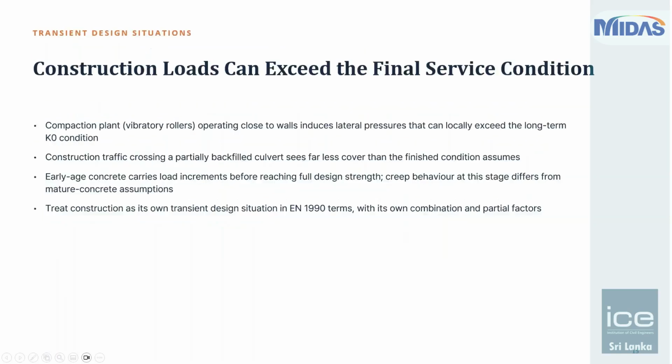Apart from that, there are certain other nuances that we must, as a culvert design engineer, understand. When we use the surcharge for design or the earth pressure for design along with the live load surcharge, right, arising from your vehicular movement, during the compaction action, during the construction stages, it is possible that when compaction is happening, the load might exceed what you have designed for. So the load might exceed the levels for which you have accounted the live load surcharge. Okay, so you will always have the earth pressure along with that the live load surcharge. What if the compaction plant load rises above the live load surcharge that you have accounted for?